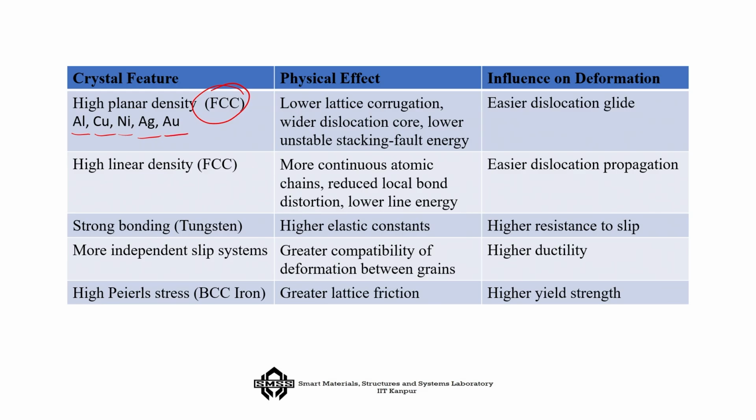All of them have lower lattice corrugation, wider dislocation core, lower unstable stacking fault energy, easier dislocation glide, exactly like I have shown you.